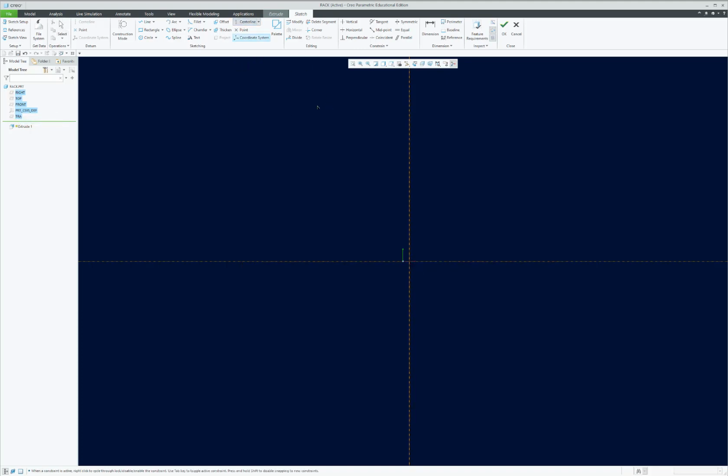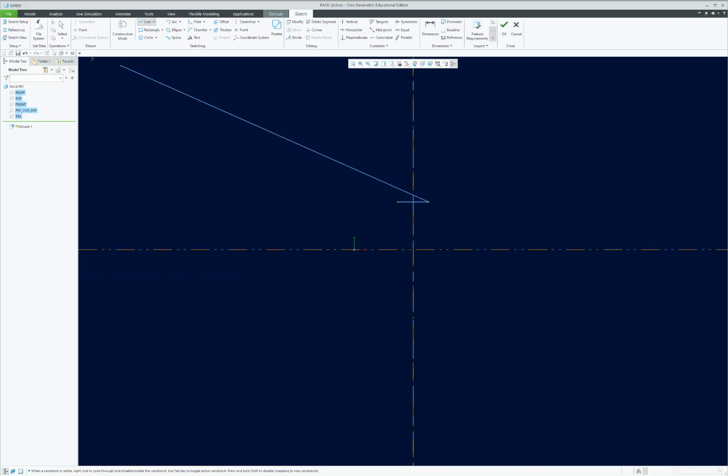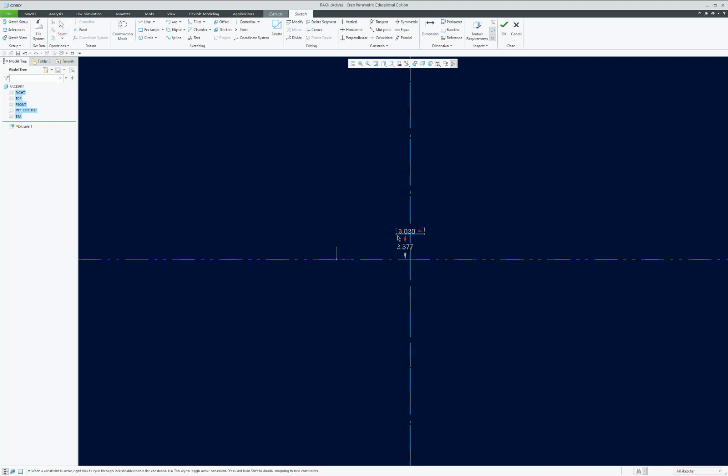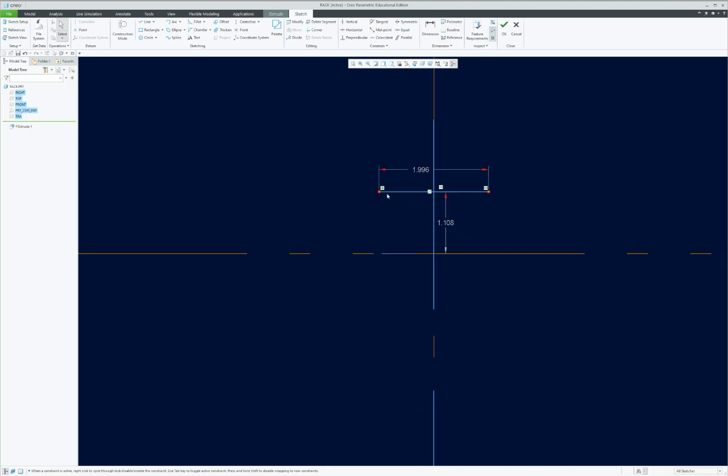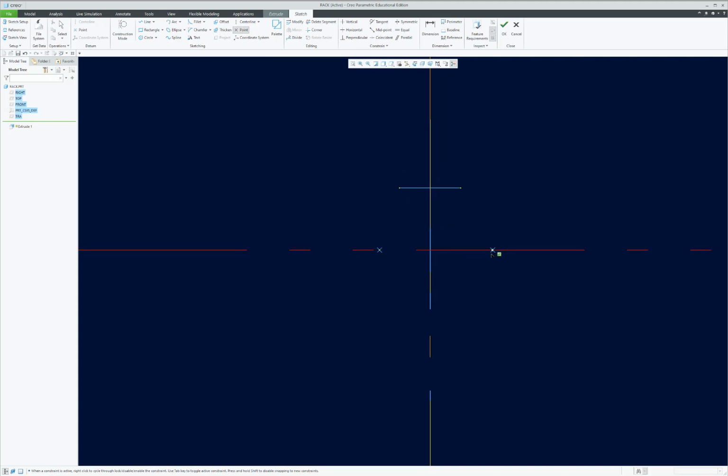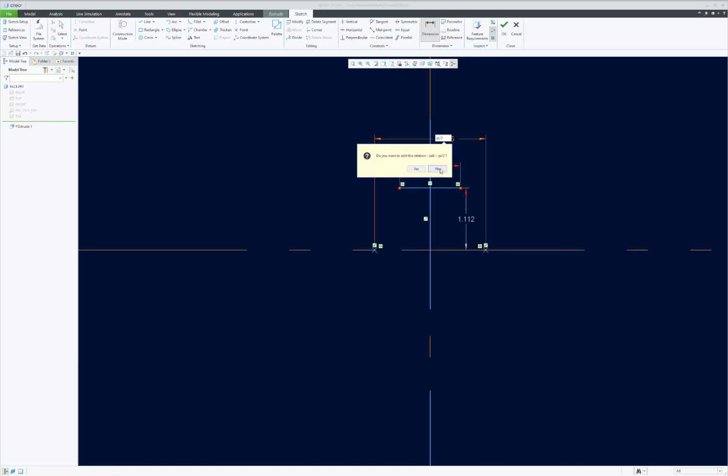Create a first vertical center line, and then here a line that snaps, zoom in, and a line that snaps symmetric. The size of this should be on the order of 1 millimeter. I'm going to take it closer to the axis and zoom in. Create 2 points, one here and one here. They should be symmetric with respect to the vertical. The distance between the 2 points from here to here is pi over 2. Enter, and I will not enter that as a relation for the moment.